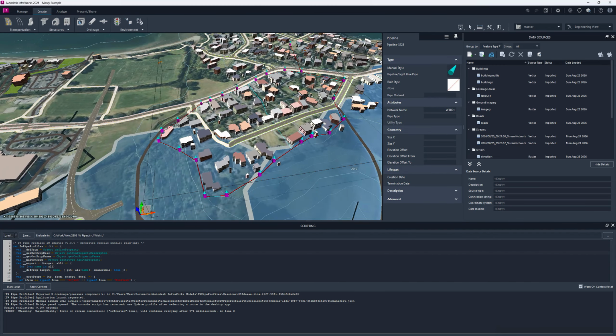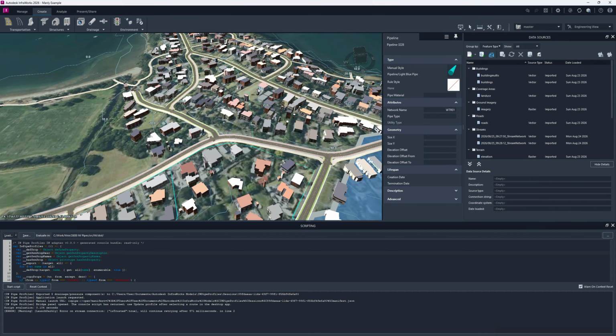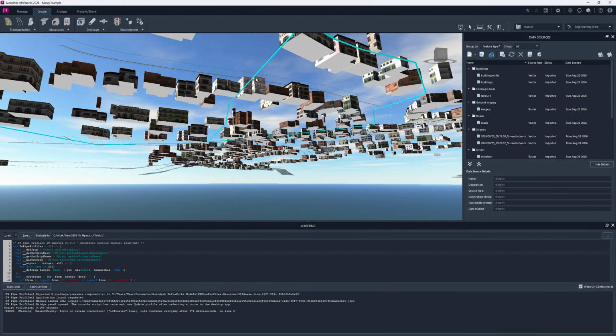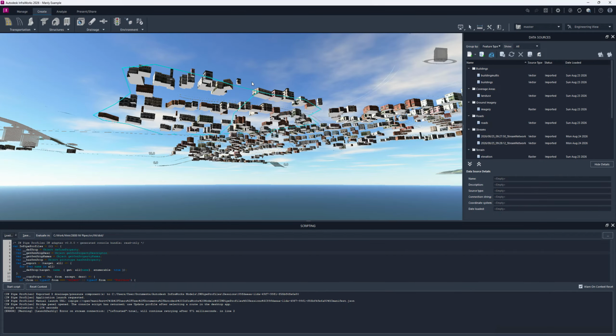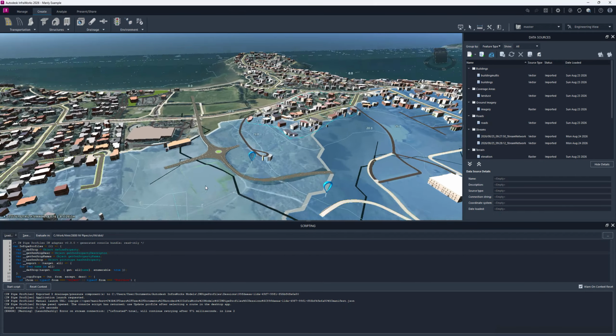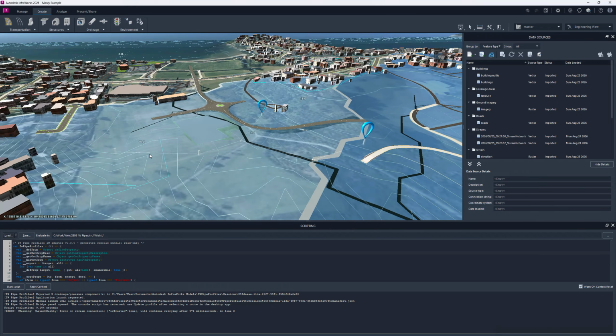All right, so that just means that I've got this little network here. You can see there are multiple vertices. It leads all the way up here where my tank's going to be, and we're just assuming that it's going to supply these houses here. So wherever we've got nodes within my pressure network is where I'm going to have nodes in my EPANET model downstream. For the drainage network, again, where we've got manholes, obviously that's where the manholes are going to be.